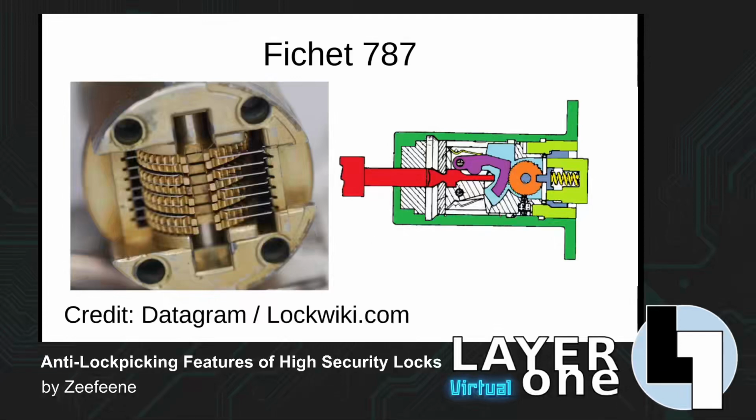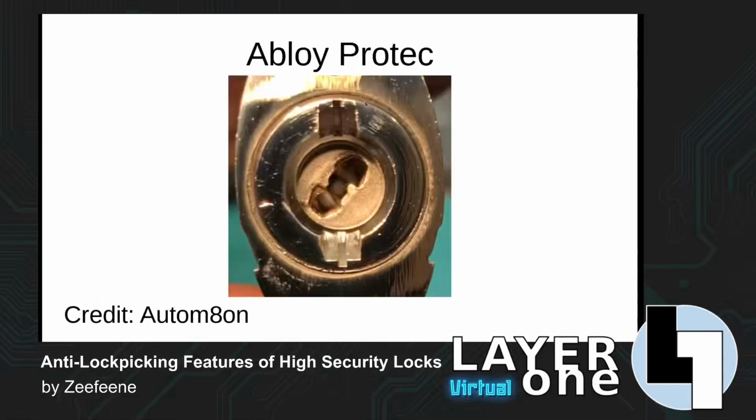And then before the gates and the wheels are tested, there is a blocking mechanism, which is this kind of blob underneath the orange gear that has to engage with the wheels or the gears before they're tested, again preventing them from being rotated, which again makes it very difficult to pick the lock.